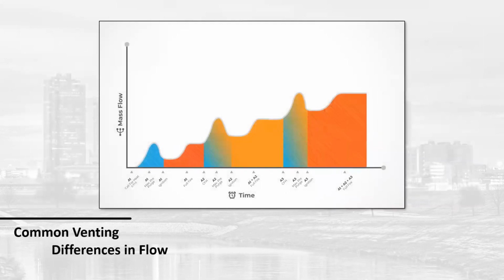And the problem is when you do common venting with high efficiency appliances, you have to size for the full load. Typically, we recommend you size for all boilers on the load. So if you have an N+1 scenario, you should be sizing that vent for all 4 appliances, assuming that three carry the load, 1 is extra.